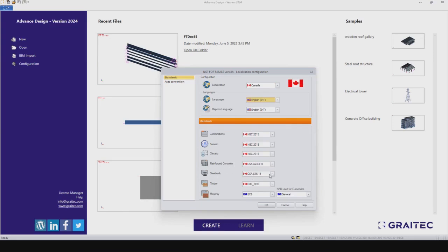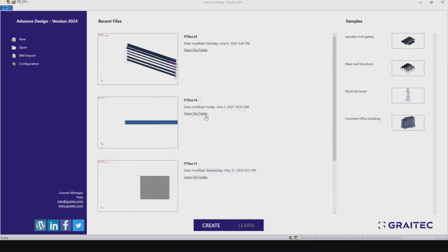And here in Steelwork, as you know, we have all of the codes, even past codes here. But the AISI S100 is accessible from here. Basically, you can select the code, and the Steelwork will be done based on the AISI code for cold form sections from here. So I can use S100-16 AISI code and click OK.